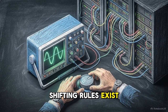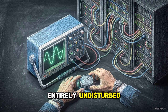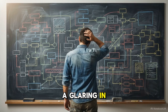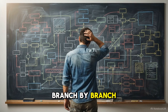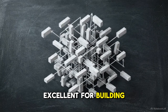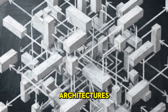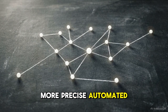These shifting rules exist strictly to guarantee that the final physical signal remains entirely undisturbed from the perspective of the overall system output. But there is a glaring inefficiency in this process. Manually pushing blocks branch by branch is highly heuristic. If you scale a single pickoff point incorrectly, that error cascades through the rest of your reduction. Block diagrams are excellent for building an initial intuition, but when applied to deep, overlapping architectures, manual block shifting becomes a liability. We need a more precise, automated tool.